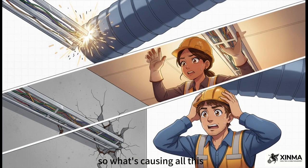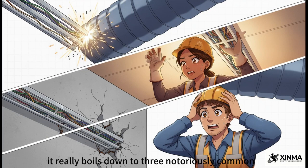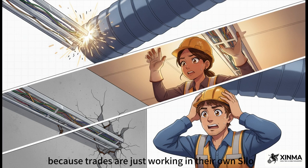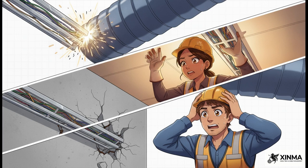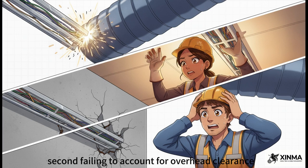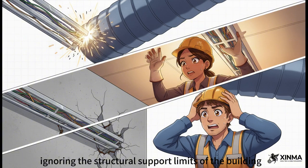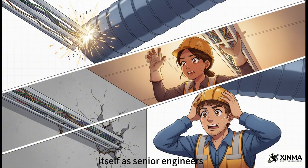So what's causing all this? It really boils down to 3 notoriously common yet totally preventable coordination gaps. First up, spatial clashes with mechanical systems like HVAC ducts. This usually happens because trades are just working in their own silo drawings. Second, failing to account for overhead clearance. Sure, the tray fits, but technicians literally can't get their hands in there to pull the cables later. And third, ignoring the structural support limits of the building itself. As senior engineers, it is our job to engineer these 3 specific gaps completely out of existence before a single piece of steel is even ordered.